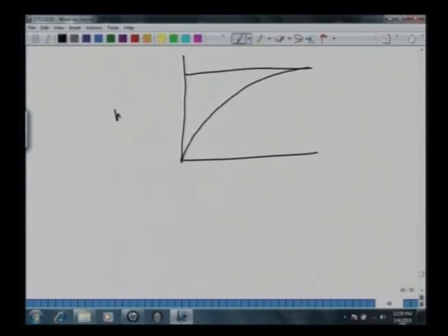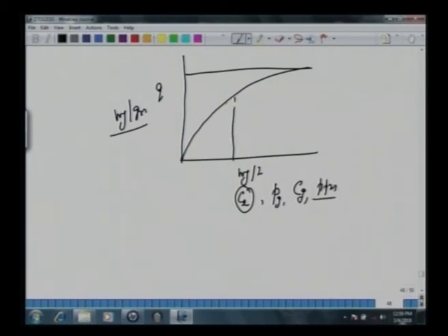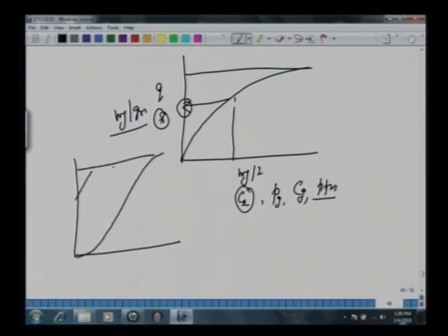So we plotted milligram per gram, say Langmuir isotherms or BET isotherms or Temkin, Q versus this concentration, milligram per liter, aqueous phase concentration, or partial pressure of the gas, or concentration in the gas phase, or ppm, mole fraction, etc. If you take this 190 ppm and read this number, this milligram per gram must be the same as what you have calculated just now from this breakthrough analysis, the area above the curve divided by the total amount of this adsorbent. The two numbers must be the same here.